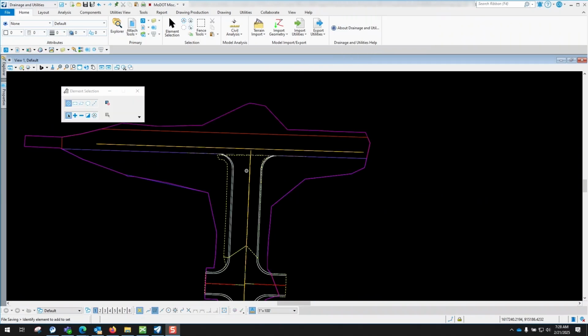The first thing that I'm going to do is create my land use areas, which would be my areas for pavement or roadway slopes, or if I had rocky area or wooded area. I'm going to create those land use areas. That way later on I can utilize my place catchment tool, utilizing those land use areas that have a certain C value. Then whenever I place my catchments for each one of those inlets, it can utilize those land use areas to compute a C value for the roughness of that particular area.